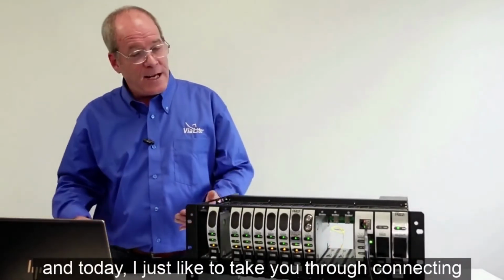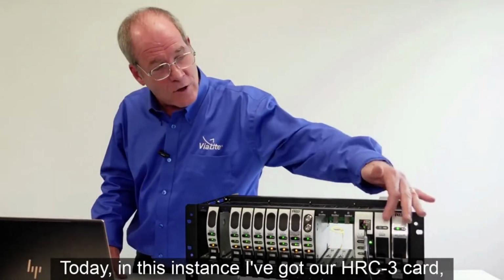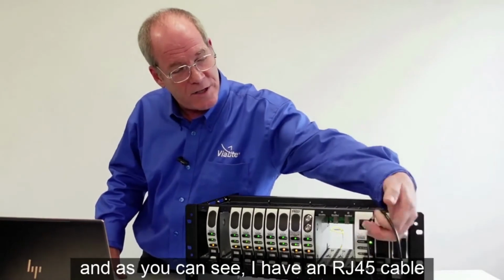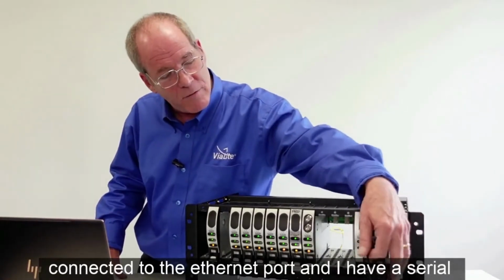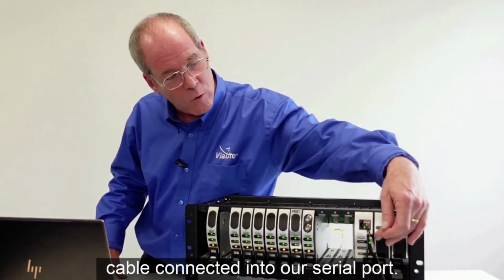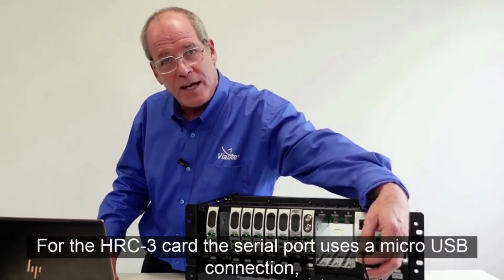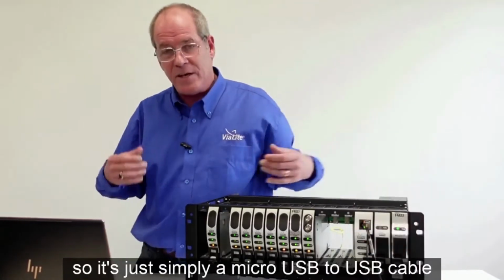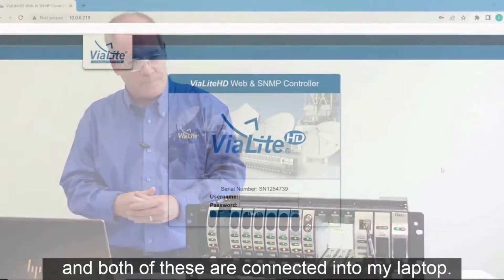And today I'd just like to take you through connecting to our monitoring and control card. Today, in this instance, I've got our HRC-3 card. And as you can see, I have an RJ45 cable connected to the Ethernet port, and I have a serial cable connected into our serial port. For the HRC-3 card, the serial port uses a micro USB connection, so it's just simply a micro USB to USB cable. And both of these are connected into my laptop.